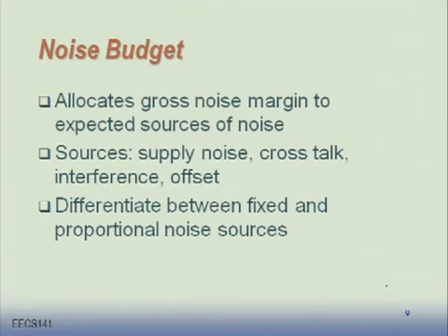I've found out what my noise margin is, the amount that is going to flip the gate. That tells me how much noise I can tolerate. Can I estimate the amount of noise that I have in the gate? More than that, I'm going to be in trouble. If it is less than that, I should be safe. So how can I guess how much noise is out there?